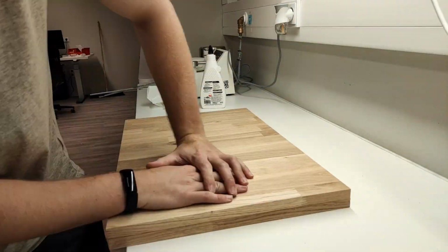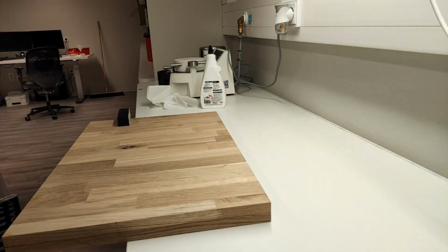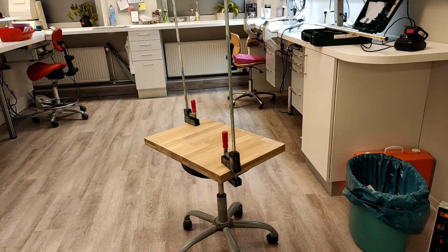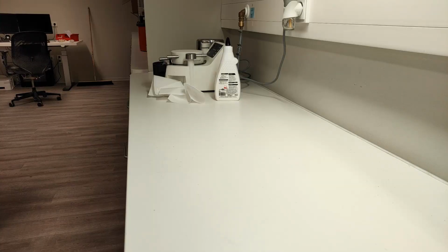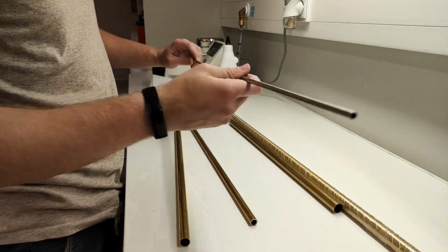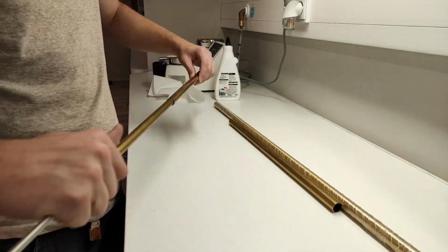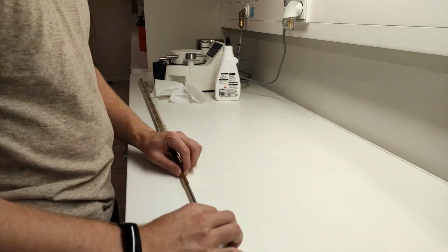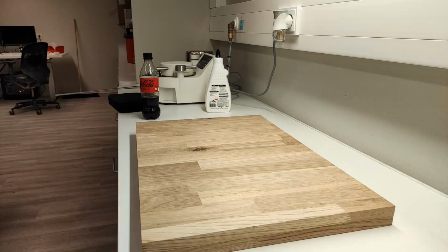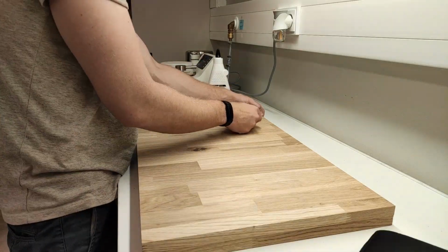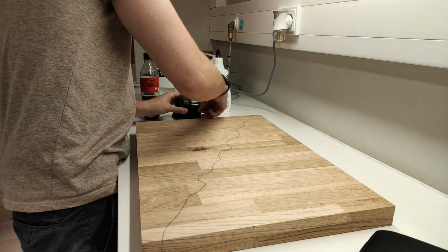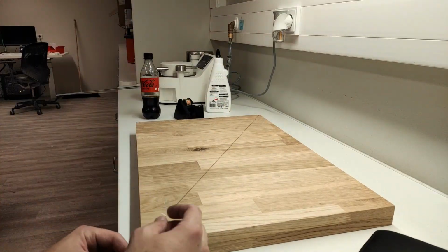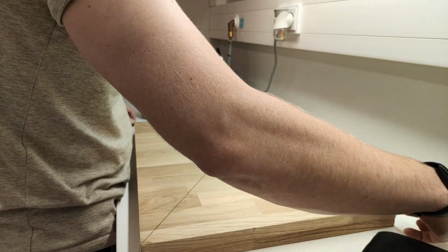To build the gearbox, I knew I would need some sort of thick base plate that I could put all of my gears onto, and I just took 2 big plates of oak wood. You can see me here gluing them together and then clamping them down in order to have a base plate. Here you can see me doing a test fit of all of the brass tubes I ordered online, and I decided to put a steel tube in the center that all of the brass tubes have as an axis they can move around. Now I needed to find the center of the board, and I basically just used 2 cotton strings attached to the edges of the base plate, and by letting them cross each other I know exactly where the center of the board is.